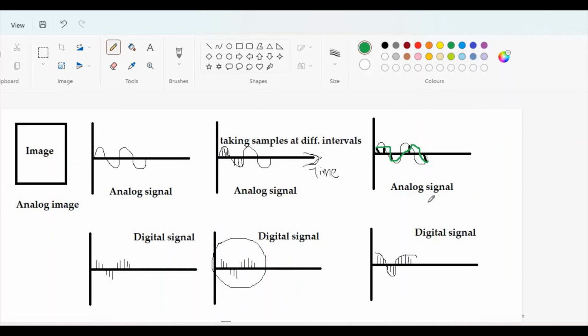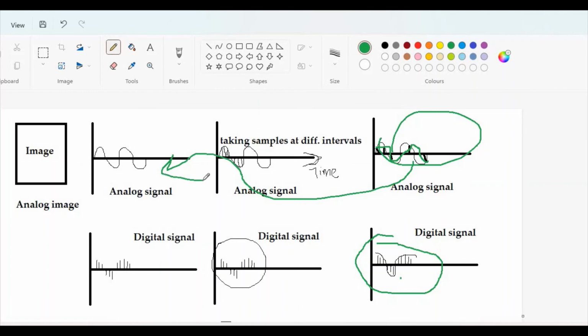If the digital signal is distorted when you're performing the conversion, due to those extra frequencies or something else, there will be inconsistencies and disparity when you try to construct the original analog signal from this digital signal. It will not be in its purest form, right?